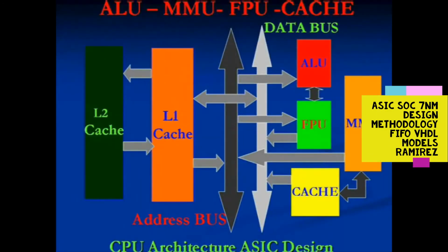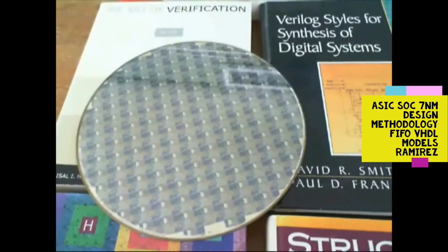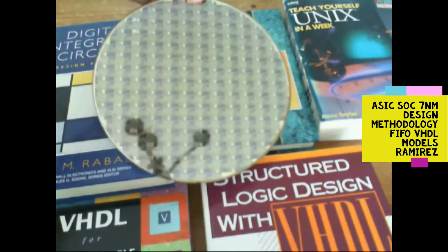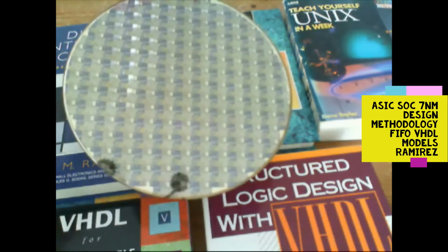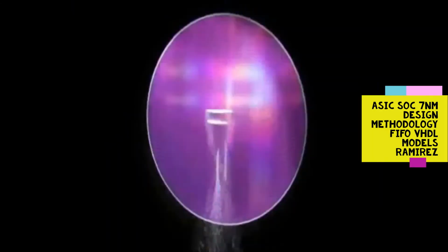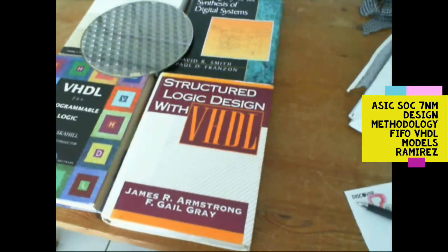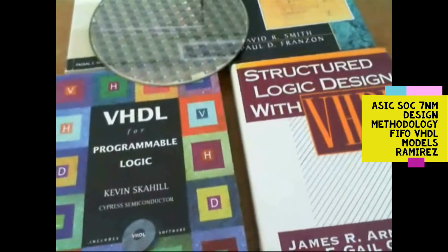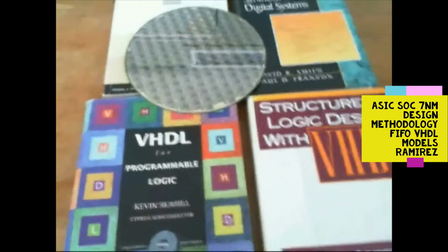Then placement of physical elements within each block and integration of all analog blocks or external intellectual property cores is performed. When all elements are placed, global and detailed routing is run to connect all the elements together. Also, after this phase, a complete simulation was done to ensure the layout phase was properly completed.